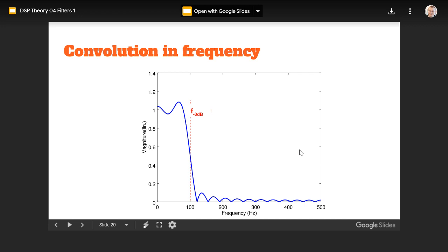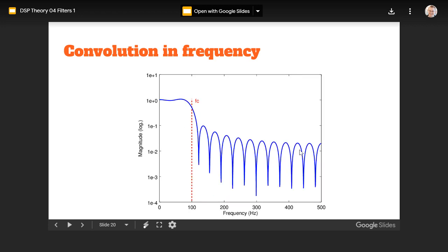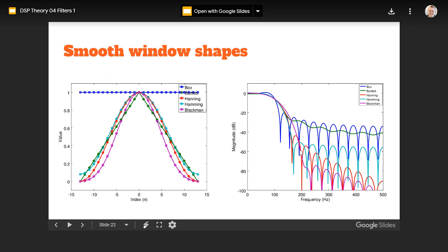But at the same time, the transition bandwidth goes higher because it has more power distributed on lower frequencies. So instead of that sinc, we would have a power density of something like this for a smoother window, more weight on the lower frequencies but a smaller portion of the higher frequencies. And that takes the stop band attenuation down.